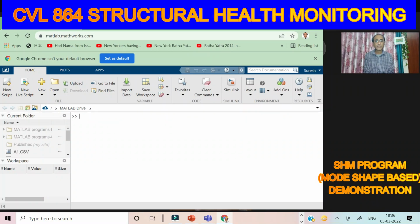The program has several versions. One version can work with the column of the FRF matrix, and you can obtain the mode shape using a column, or alternatively you can use the row. Column basically means that we are varying the location of the force and our measurement is at one point, and row means that we are exciting at one point and concurrently measuring the response at multiple points.